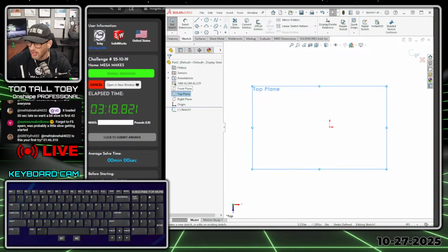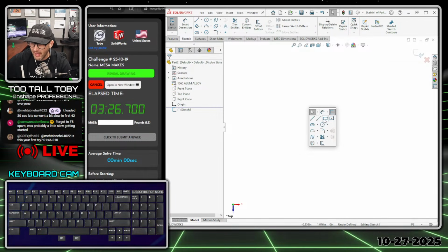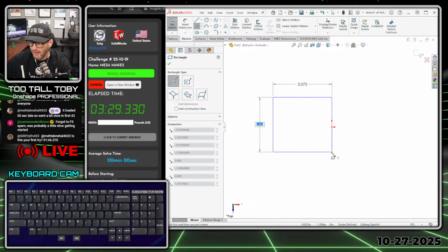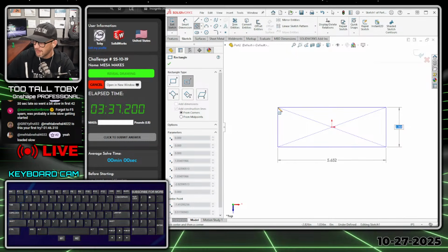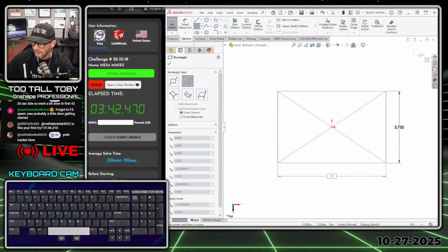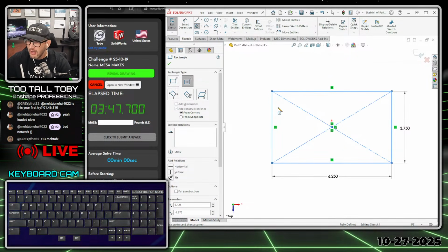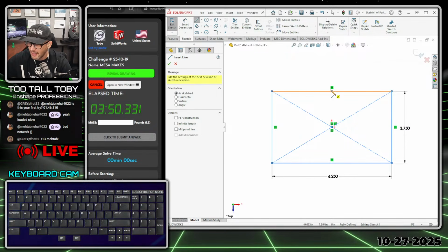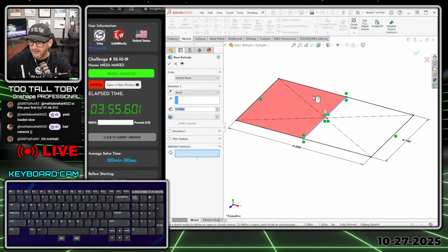And now that we've got that sketch up and running, let's get into our 3D CAD and let's start modeling this thing up. So we said before that our first sketch is going to be on the top plane. So S key, rectangle, single click, move my mouse, single click. I could certainly draw it this way, or if I wanted to, I could just draw a rectangle to the total dimensions. So this is going to be 3 space 3/4, and this one's going to be 6 space 1/4. That's how you can do your fractions as part of your inches. And then I can just draw a solid line going right down through the middle here. What that's going to do is let me then take that geometry and extrude it by selecting a contour.